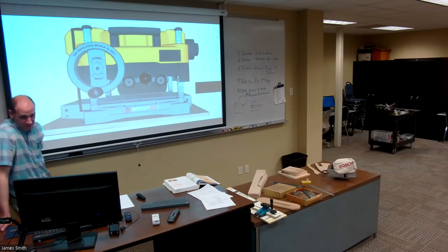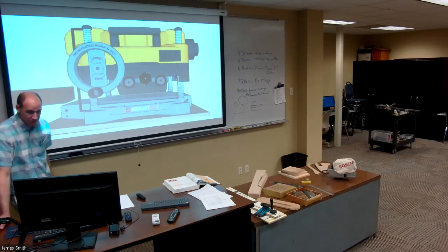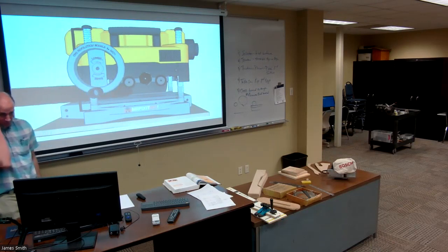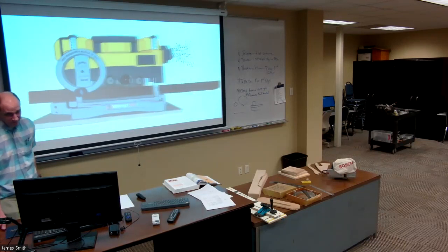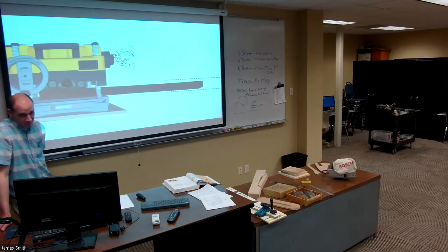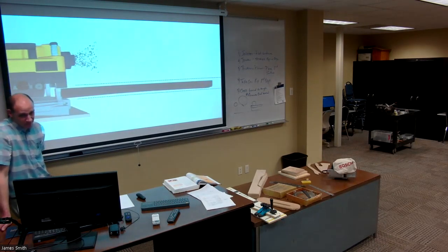Now let's see what happens if we do this with a piece of wood that has a bow. As you can see, as the piece is fed through the machine, the roller is pressed down on the piece of wood and it follows the bow. So while you'll end up with a piece of wood that's uniform thickness, it won't be flat. If you put the piece over and feed it through the machine, the rollers will push down on the bow and flatten it out as it goes through the machine. But as it comes out the other side, the board will spring back to its original shape. So while your board will be uniform thickness, it still won't be flat.